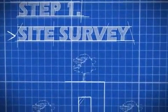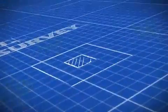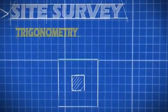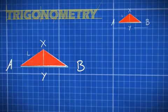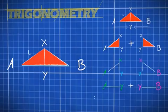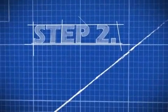First things first, we need to survey the site. We need to ensure that the building fits within the proposed site. However, there's a tree getting in the way of measuring the position of the south wall. The blue line represents the south wall. Let's call it AB. Utilizing Pythagoras' theorem, we can measure AX, BX, and the offset XY to find the distance of AB.